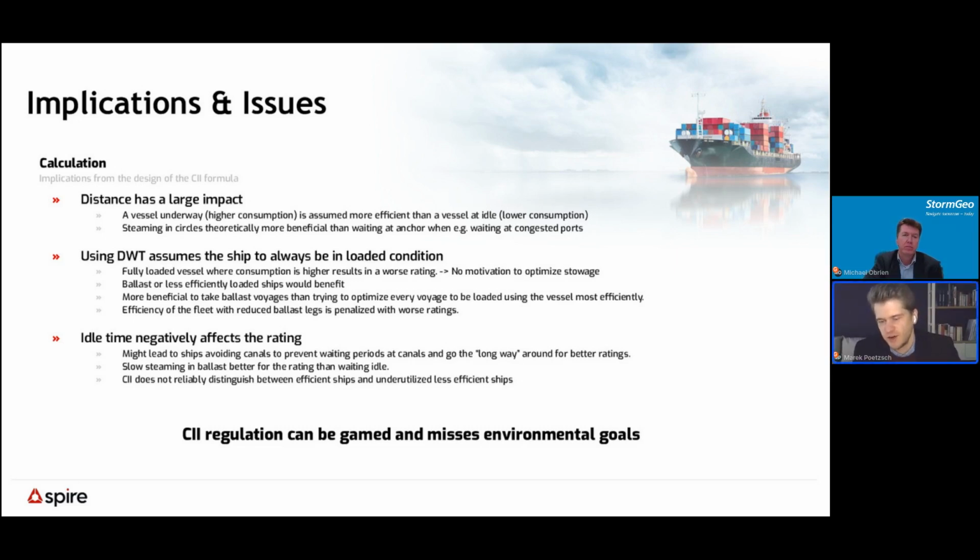Not using the actual cargo carried removes the actual efficiency of the vessel in an economic sense, where it doesn't matter how much cargo the vessel actually carries, and it just always assumes the deadweight. And then, idle time very negatively impacts all ratings, because the consumption for the whole year is taken, and also the distances for the whole year.